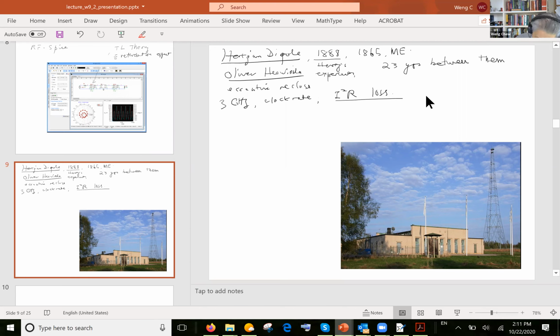And you can understand this loss quite easily by using a very simple model. You have a CMOS transistor, which approximately can be thought of as a capacitor, because it has an insulating layer between the gate and the substrate of the CMOS.